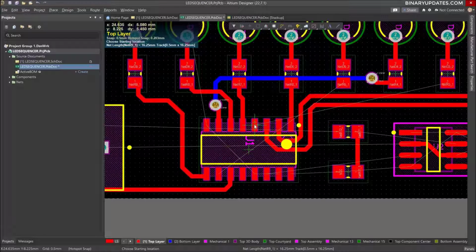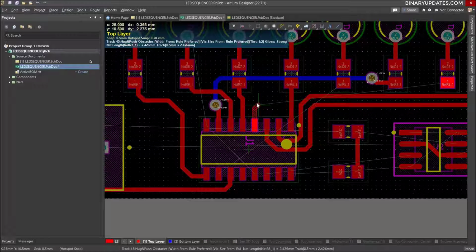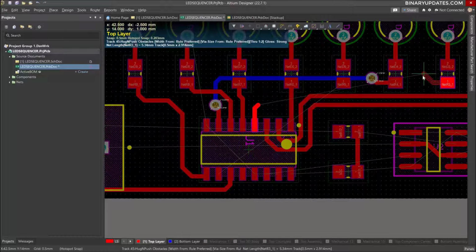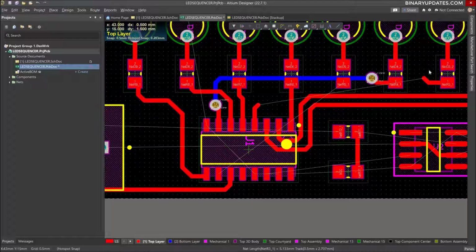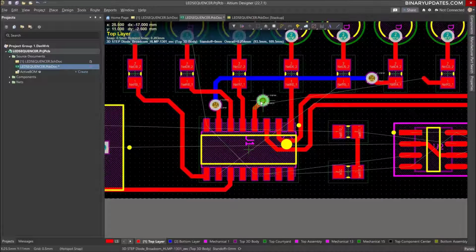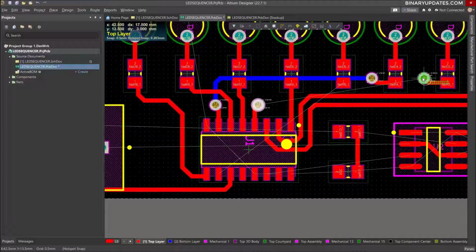So look at this one. This point should connect to this resistor, and I can use vias again for this. So I would just put one track here on a top layer, and then I make one more track I can draw here. Click and right click, and then press escape, and then I would place the vias. So select the vias, place vias, and put one via here, and put one via here, and press escape to get out of vias.